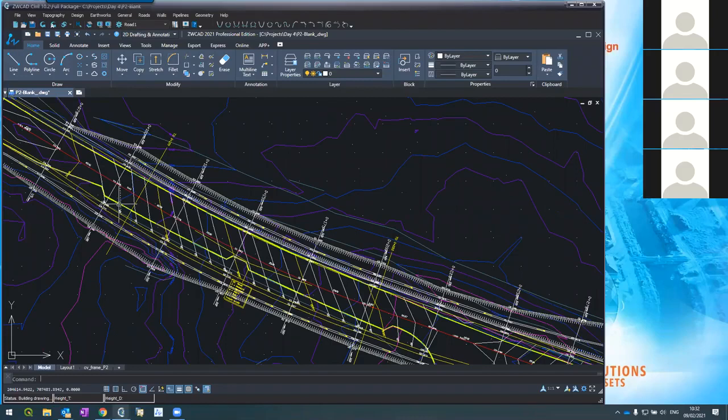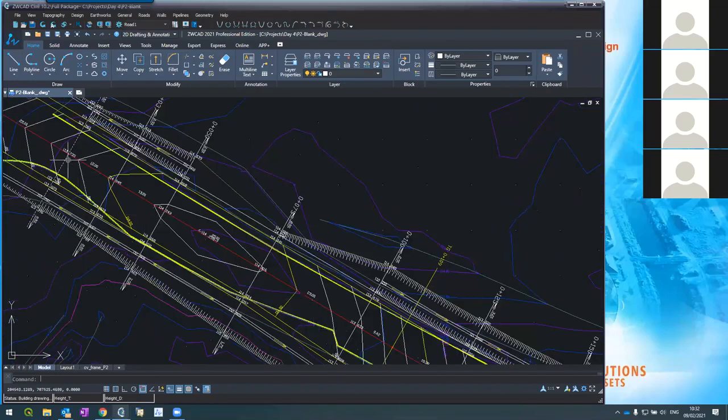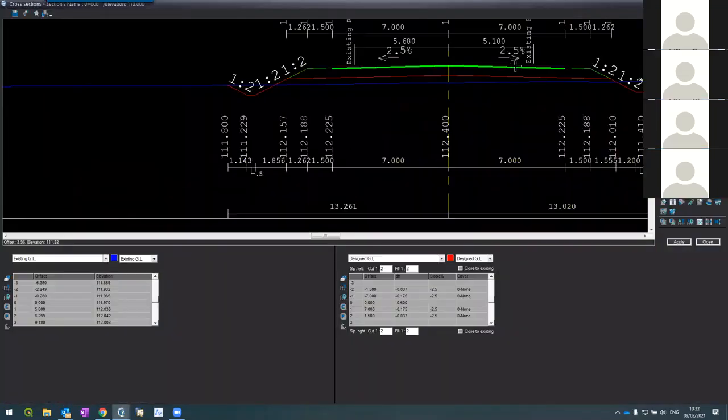Obviously, the main lane which is super elevating is the right lane. Right lane, yeah. Why? Because the right lane has 2.5% going this way, right? If I go to cross section, one second. This lane is 2.5%. If I'm turning to the left, I have to super elevate it. Right? Yes, sir. I have to super elevate this lane.